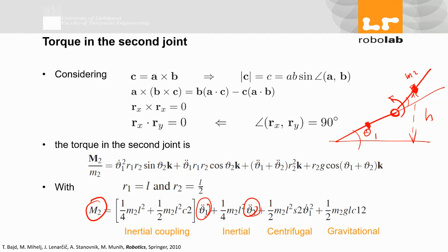The order doesn't matter. You have to look at it. You're talking about link 2. So theta 2 is something of itself, right? You have a mass, and that's the inertia of that mass. But you also see the second derivative of theta 1, which is inertia for mass number 1. This is because these two are linked together. These are coupled together. Does it make sense now?